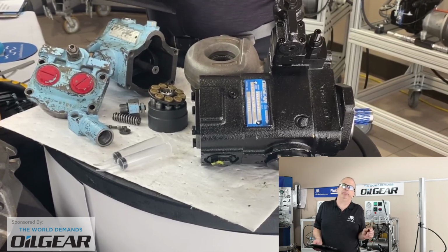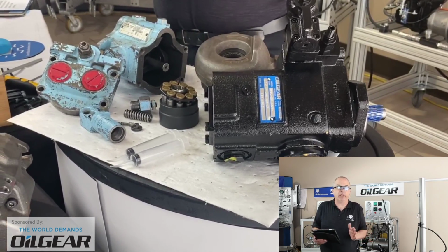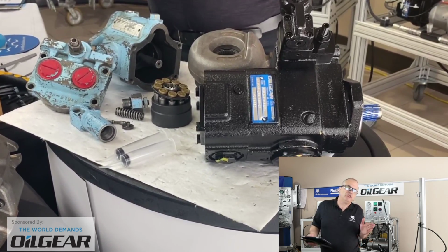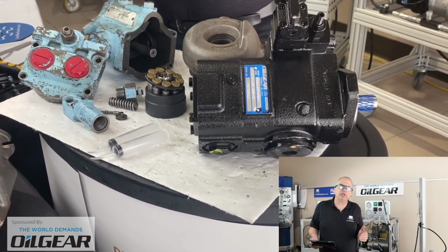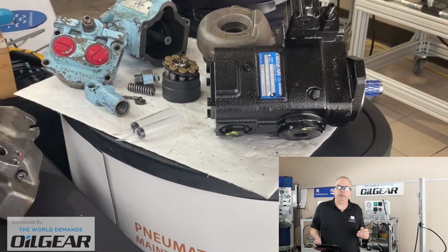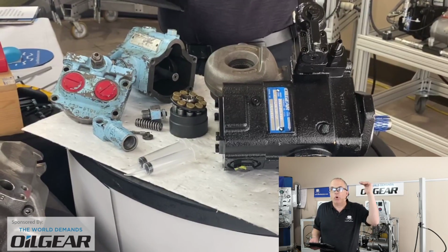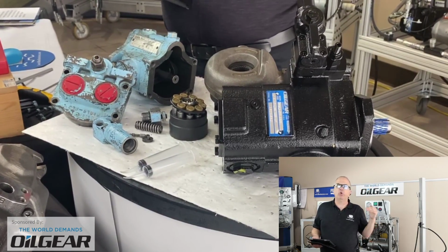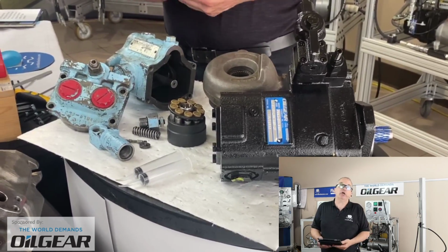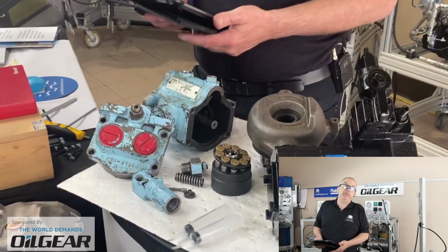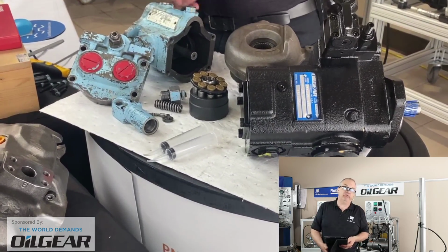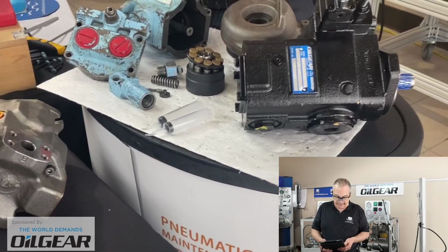so that the relief valve and the pump's pressure compensator never have a moment where they might overlap and both try to react to a high pressure condition. So it tends to run the range of having the relief valve set 150 psi higher to sometimes having that relief valve set up to 400 psi higher. So check with the manufacturer of your machinery, your hydraulic system, or check with the manufacturer of the pumps that you're going to use and see what they recommend there. There is a bit of a variance out there on that topic.